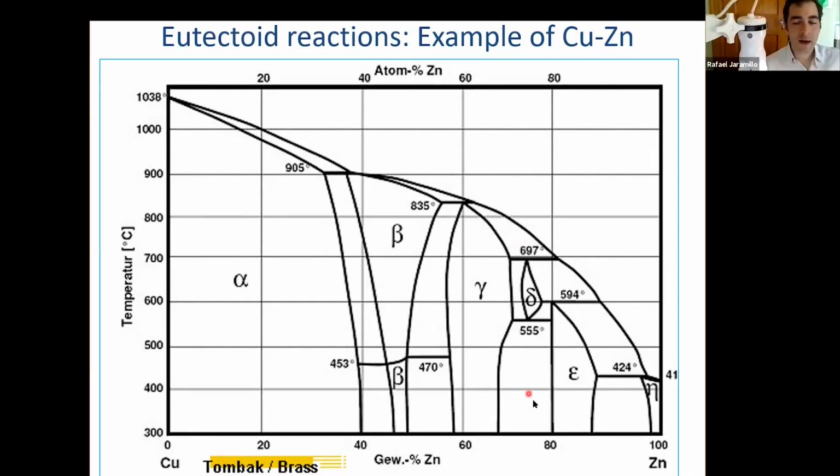I have gamma and epsilon. Heat up, heat up, heat up, gamma and epsilon, heat up. Sudden transformation. Everything mixes spontaneously into a new crystal structure, delta. Heat up, heat up. Oh, suddenly I have spontaneous unmixing again. But in this case, it's into two phases, back to the gamma solid crystal structure and some liquid. And as I heat up further, the liquid phase fraction increases, hit the liquidus, and now I have one liquid solution. Right, okay. There you have it. One solid phase to two solid phases.